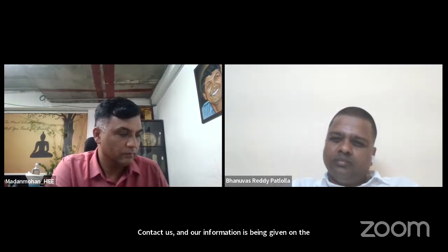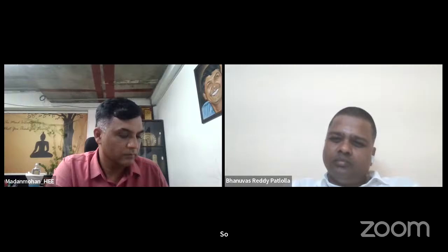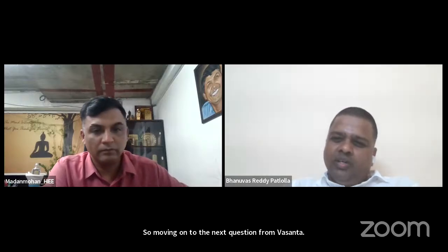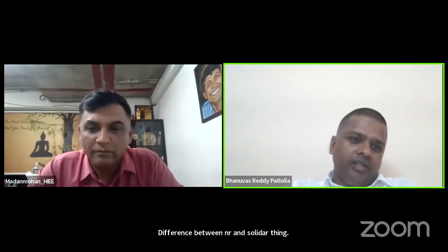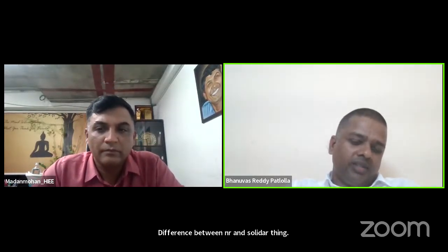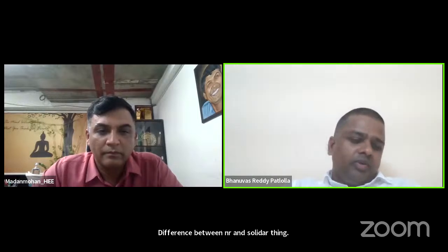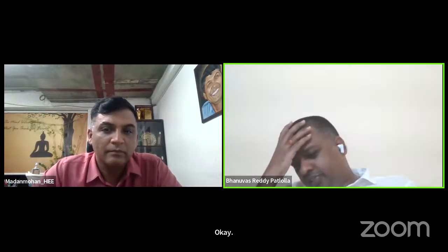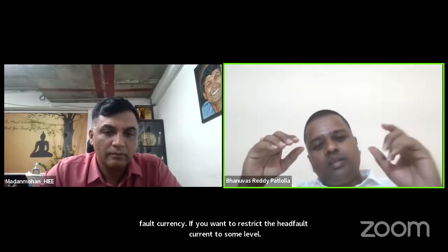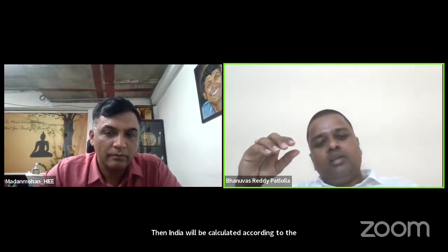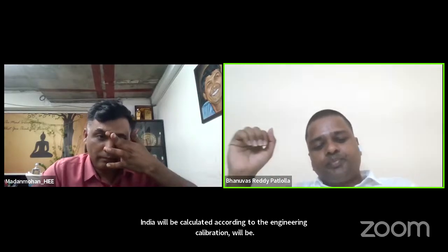Moving on to the next question from Vasanta: difference between NGR and solid earthing. NGR is for restricting the earth fault current. Solid earthing has no restriction on earth fault current. If you want to restrict the earth fault current to some level, then the NGR will be calculated according to the engineering calculation. The earth fault current will be restricted to some extent.